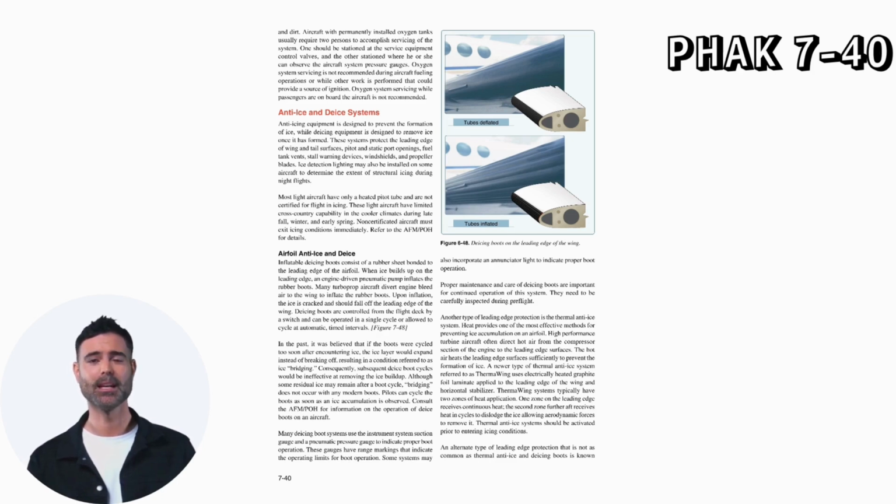Another type of leading-edge protection is the thermal anti-ice system. Heat provides one of the most effective methods for preventing ice accumulation on an airfoil. High-performance turbine aircraft often direct hot air from the compressor section of the engine to the leading-edge surfaces. The hot air heats the leading-edge surfaces sufficiently to prevent the formation of ice.